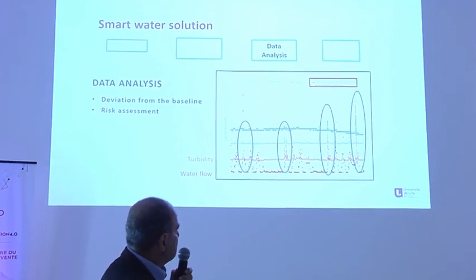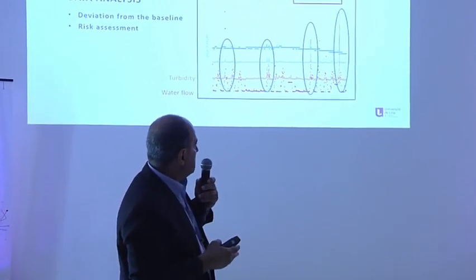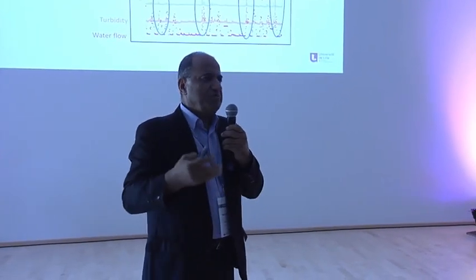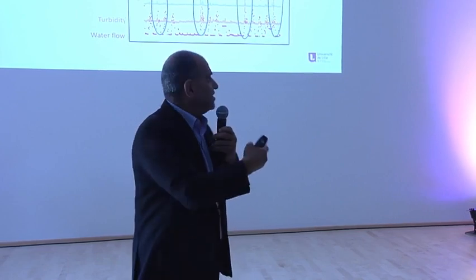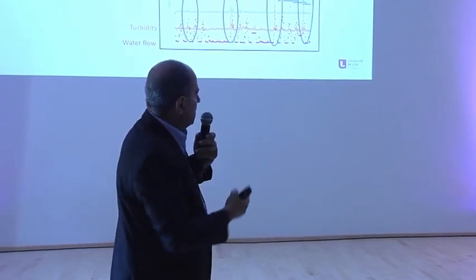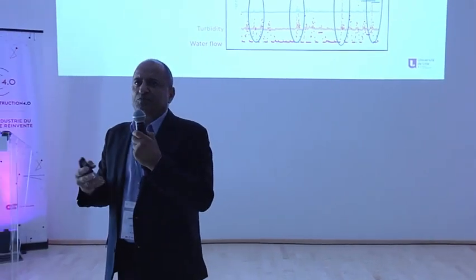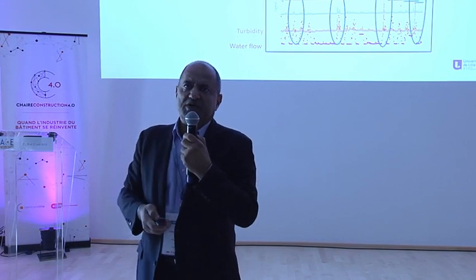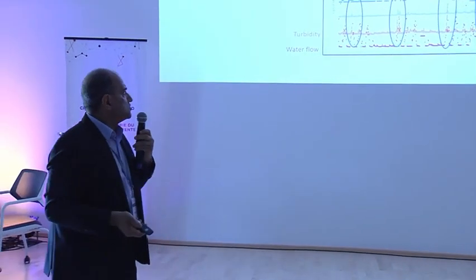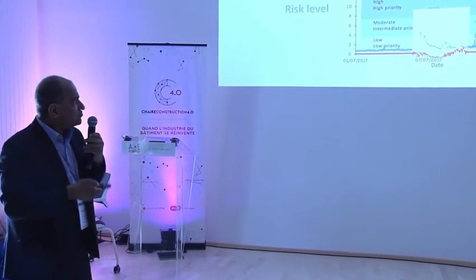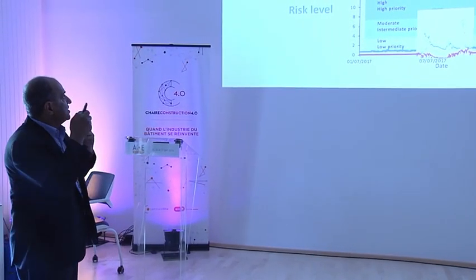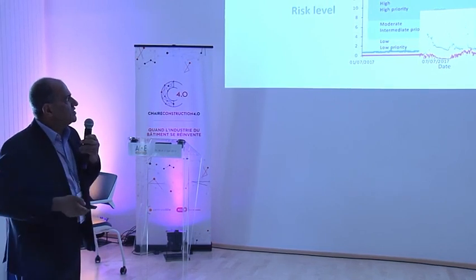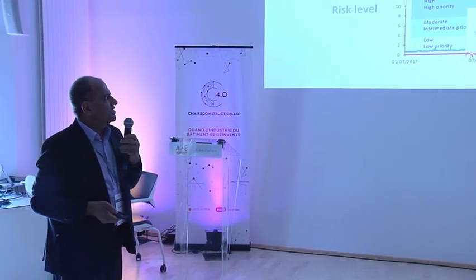And this something was mainly in the morning when students come into the building and the water flows, because we have some stagnation and so on. It means that if we cannot change our pipes, we can, before the students come, flush our network. This result also was very important, and we also made some risk analysis concerning the likelihood and severity, and using this analysis, we can decide what is the level of risk concerning the water quality.